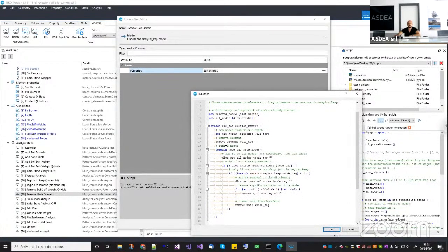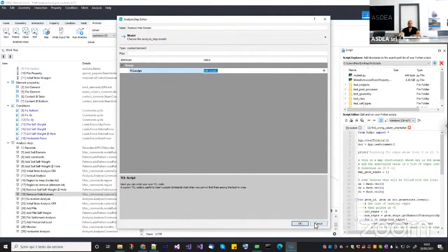Here I'm saying remove the element, but I'm taking for granted that this element is available on the partition where this code will be called. But this is not true, because one element is available only on one of many partitions. If you have just one partition, or if you do sequential analysis, this code is fine. If you want to use the same code with parallel analysis, it will not work. It will just give an error in OpenSees. So you cannot use this one.